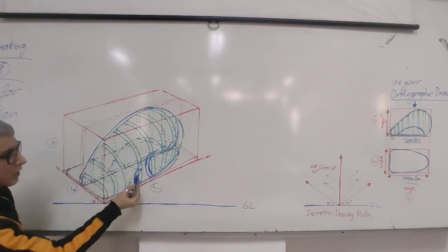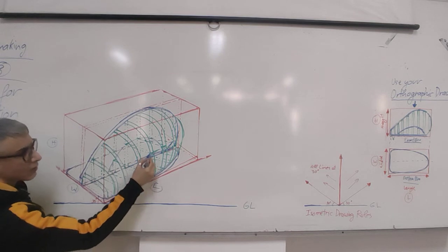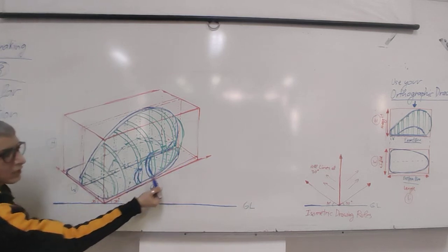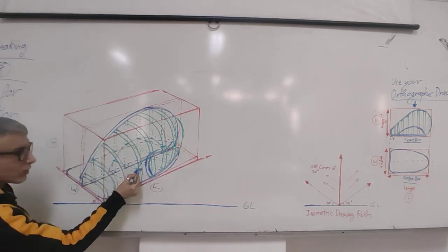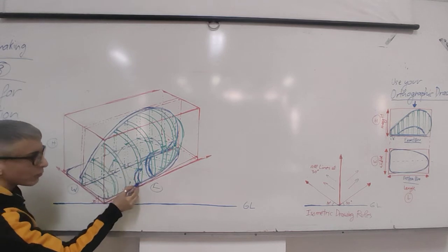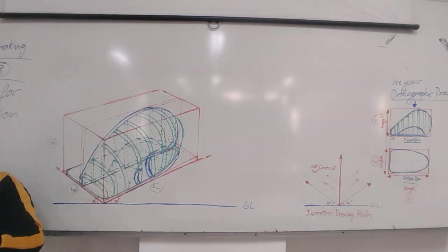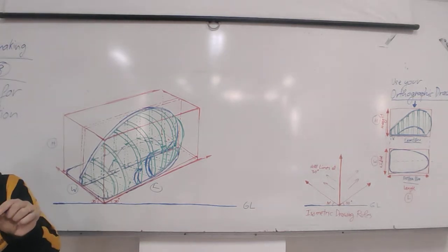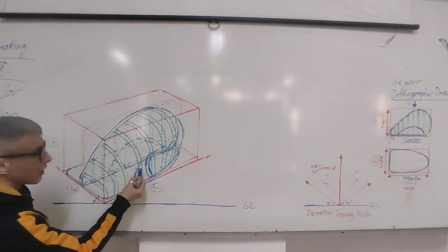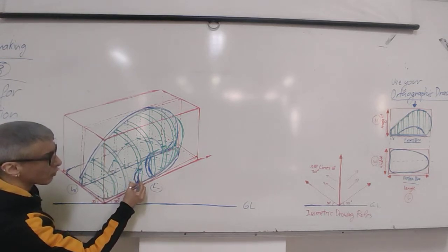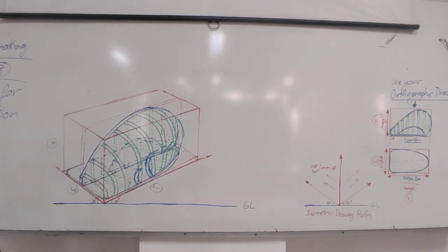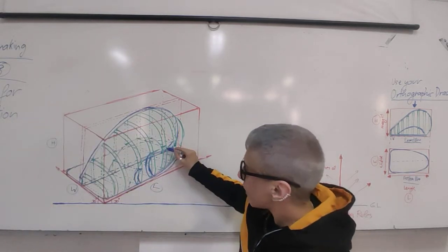Be careful, each of these lines here must be what? At 30 degrees. Whatever the shape is here, it must always be 2 millimeters. Don't make it, for example, thin here and go larger. It must be all the way 2 millimeters, so be careful on the drawing. Not the way my hand drawing looks, okay? Be careful. Then what happened here?